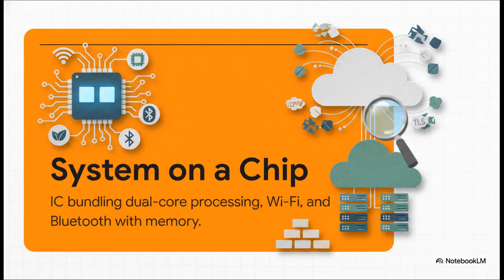To kick things off, let's look at why this chip really is the gold standard for IoT projects right now. The ESP32 isn't just a basic microcontroller. It's a highly versatile system on a chip. It is packed with raw, dual-core processing power. It can handle incredibly heavy communication stacks, like TCP/IP and TLS, without even breaking a sweat. Plus, it bundles Wi-Fi, Bluetooth Classic, and Bluetooth Low Energy all into one single integrated package.